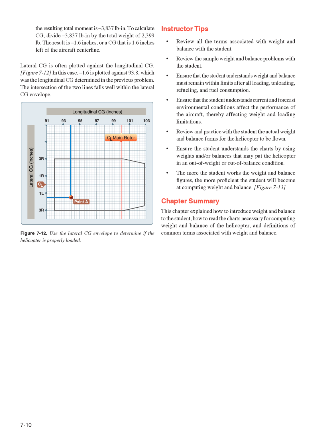Instructor tips: Review all the terms associated with weight and balance with the student. Review the sample weight and balance problems with the student. Ensure that the student understands weight and balance must remain within limits after all loading, unloading, refueling, and fuel consumption. Ensure that the student understands current and forecast environmental conditions affect the performance of the aircraft, thereby affecting weight and loading limitations. Review and practice with the student the actual weight and balance forms for the helicopter to be flown.